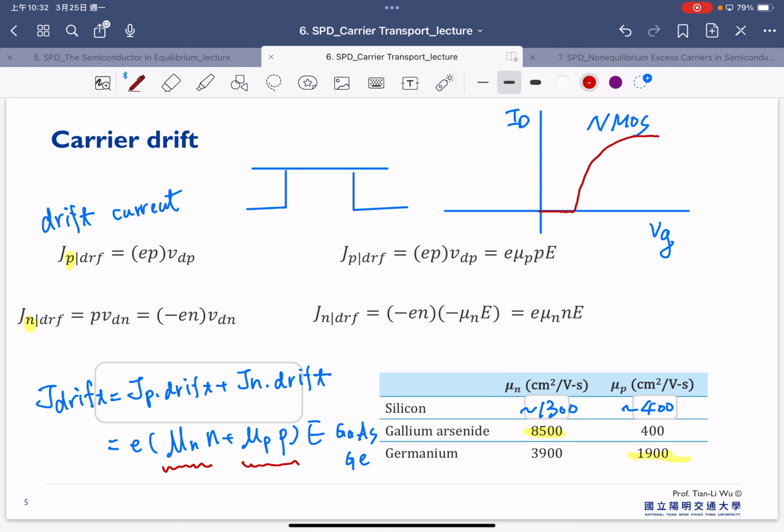And this is in the case, for example, let's say if we use a silicon material here, and then the current increases under the positive gate bias. This is because we start to have the electrons. We usually call this an inversion channel. Later on, when we talk about MOSFET, we will talk a little bit more about why we call this inversion. But at this moment, just try to accept there's a term called inversion. So this is electron inversion in P substrate.